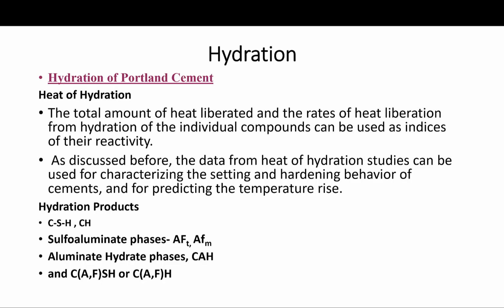Such Portland cements, as I mentioned, are no longer readily available, so there are other options. The hydraulic cements meeting similar heat of hydration requirements, that is type LH, low heat cement, and the type MH, which is the moderate heat cement. Those can now be marketed under the performance specification ASTM C1157, which does not restrict the composition or the constituents of the cement. So it's just performance based. If it meets the heat generation requirements, then it is acceptable.